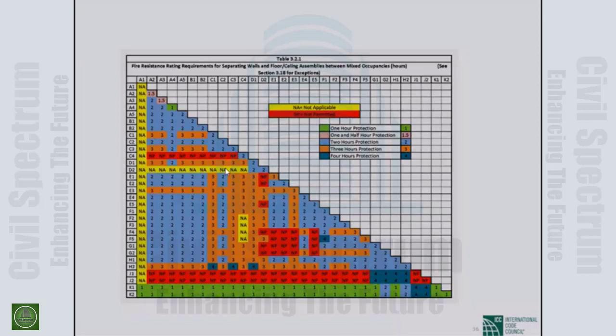So if you like to make a hospital and the medical college side by side in a building, which is prevailing in Bangladesh in a lot of areas, then you need 3 hour separation. But I did not see any private hospital or medical college here that has 3 hour separation. They are doing the wrong thing as per BNBC. They should be careful about their firefighting system because they are not allowing this 3 hour separation. So I hope you understand this critical thing.